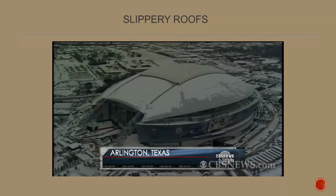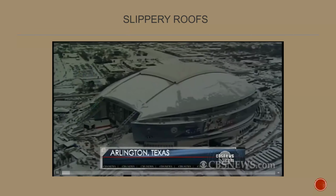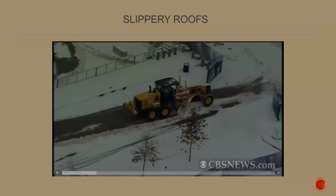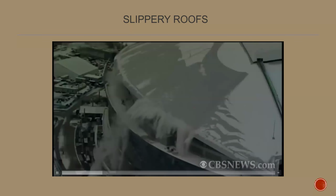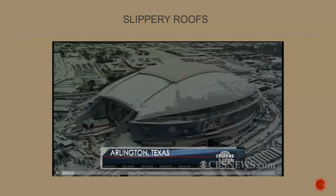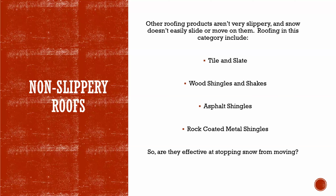And they decided against snow retention because Dallas just doesn't receive that much snow. But due to those situations, not only did they have to install snow retention, but the day of this storm, firefighters were up on that roof with fire hoses spraying off the ice in the gutters. And due to that, the TPO of the roof was actually sprayed off as well. So they had to do a full re-roof on this and then install snow retention while also closing out a massive lawsuit. So if you're designing in snowy regions, you most definitely need to be considering the snow.